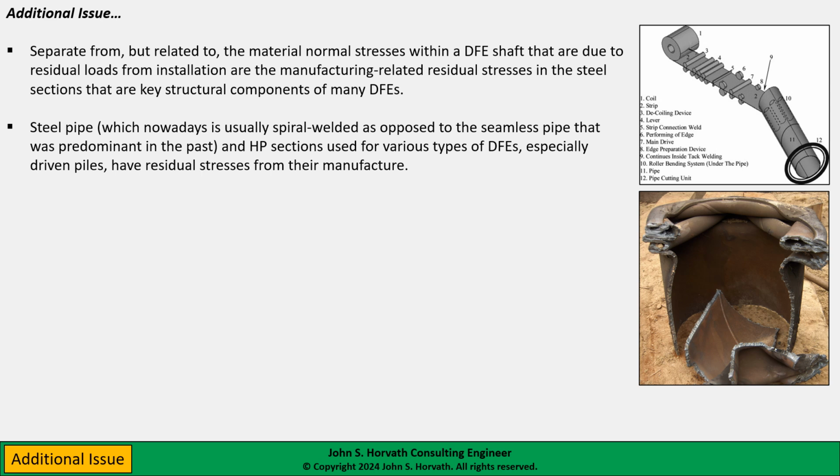This was a tapered tube pile where the head of the pile was not properly lined up with the ram of the pile hammer during installation. And as you could see, because of the driving eccentricity, the upper few inches of the steel pile yielded. Now keep in mind, this is 50 ksi yield steel, so this is stronger than average steel. So you could see really this classic kind of accordion yielding of the upper few inches of pile as the steel stresses were greater than yield. What to me is enlightening here is notice that the welds did not separate.